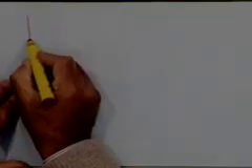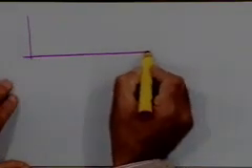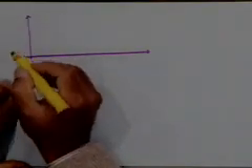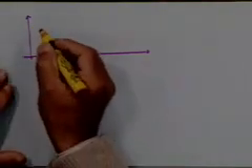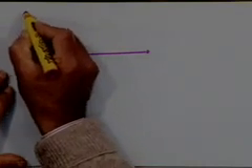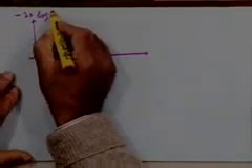For example, I'll give you typical attenuation characteristics that you might see in a telephone channel, for example. Usually these magnitude characteristics are plotted on a log scale. So I'm plotting here minus 20 log of |H(f)|.